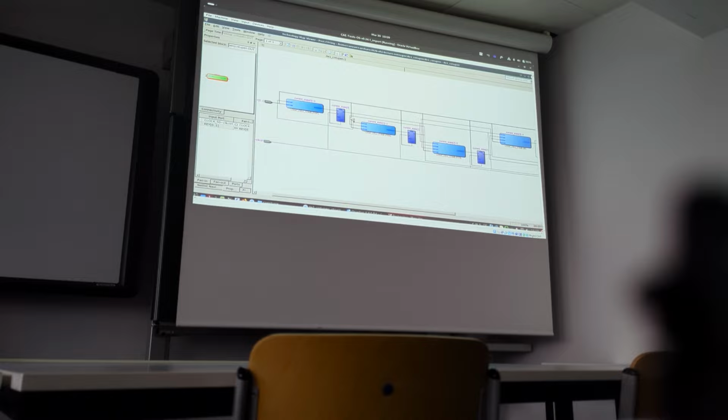In the usual way, we know from basic digital electronics how to design a simple up counter. Additionally, you see the logic cells here. So it uses a logic cell for the combinational logic part for the first flip-flop, another logic cell for the next flip-flop, another logic cell, and so on. You remember maybe that the arithmetic gets more and more complex from stage to stage.